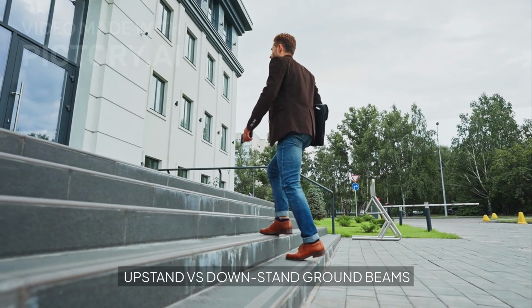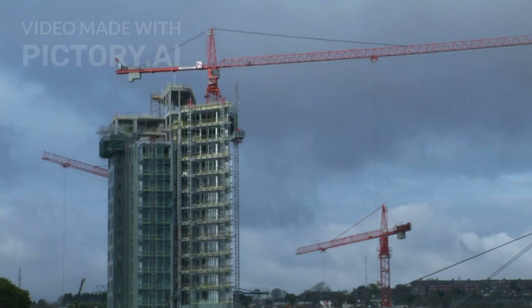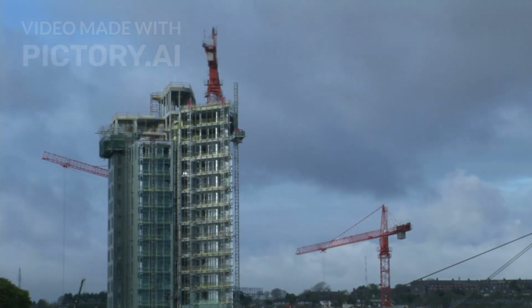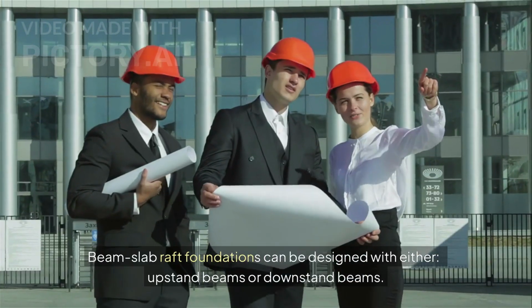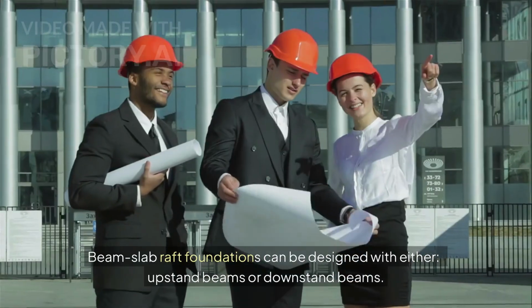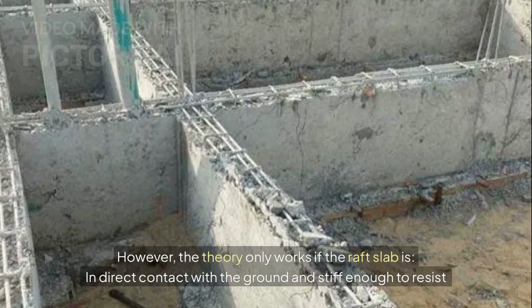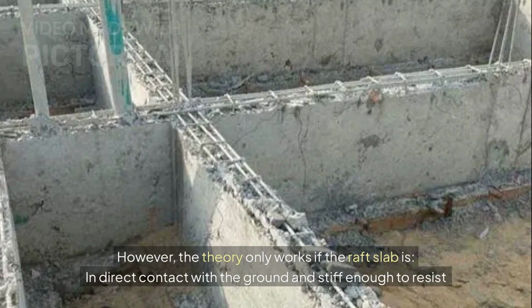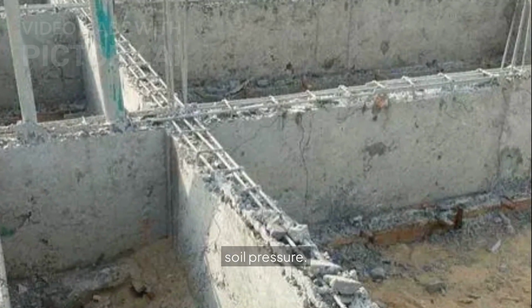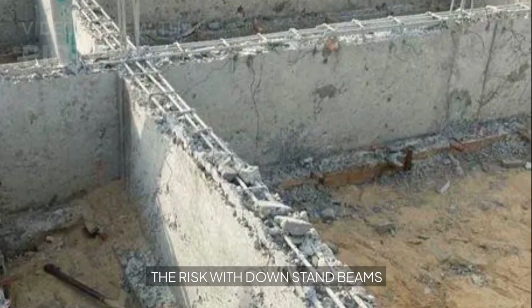Upstand versus downstand ground beams. Beam-slab raft foundations can be designed with either upstand beams or downstand beams. However, the theory only works if the raft slab is in direct contact with the ground and stiff enough to resist soil pressure. The risk with downstand beams.